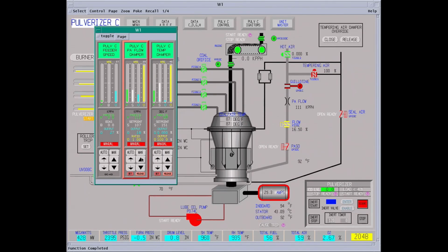You want to be kind of careful too when you bring up the air. You're loading the primary air fans. We have a whole bunch of coal nozzle temperature alarms coming in. They all cleared. It's just about 500 degrees, most of the nozzle temperatures. Now if you move your air too fast, you can reject your primary air fans, which means they kick back to manual, drop out of automatic.